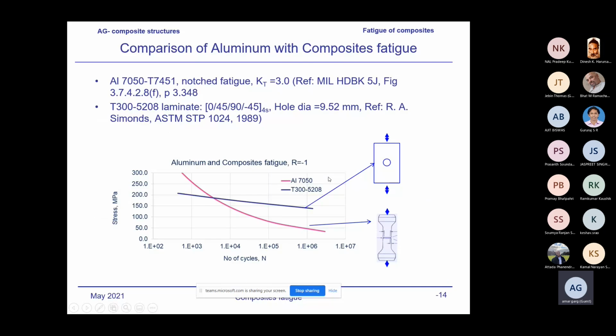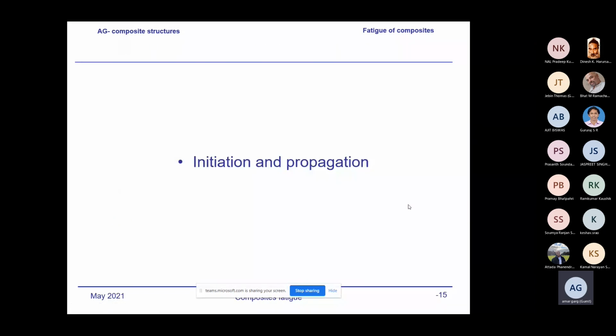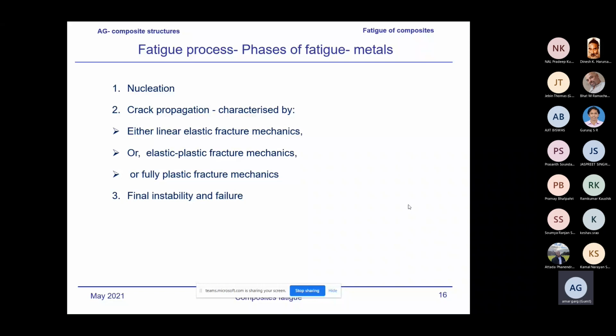Here is an example I had plotted, showing the difference between aluminum and composite for the damage. You can see the aluminum has a very steep S-N curve compared to the composites. So that's the advantage of composites: they are better in fatigue. Initiation, progression, now I'm going to...